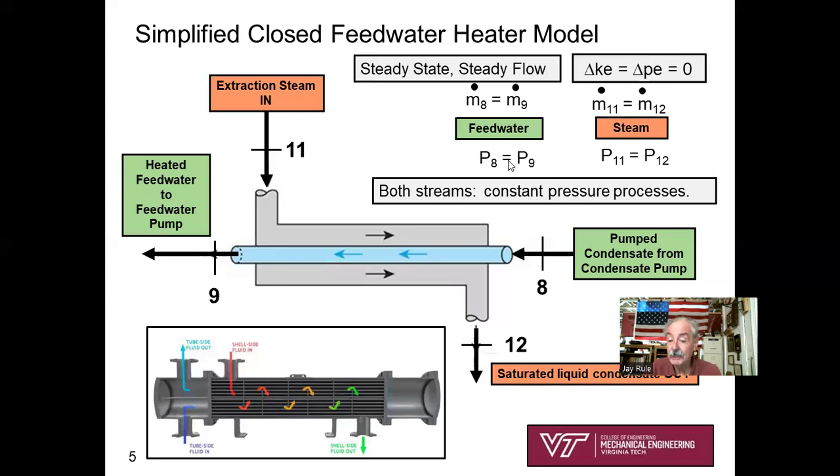And also our model is going to be that P8 equals P9. It's going to be a constant pressure process, and no work is involved, is it? We don't see a weight being lifted. We don't see a shaft coming out.